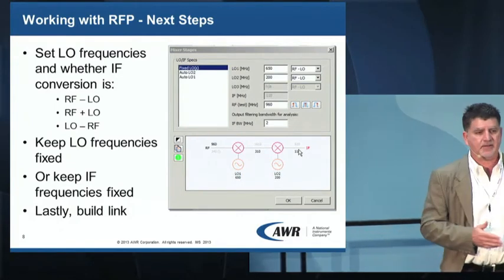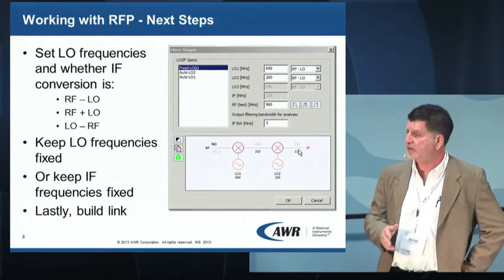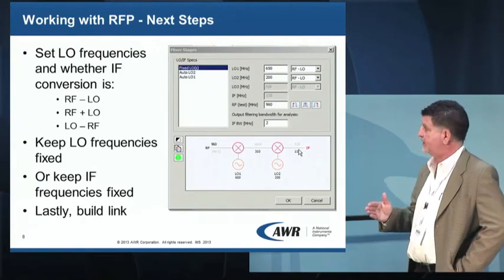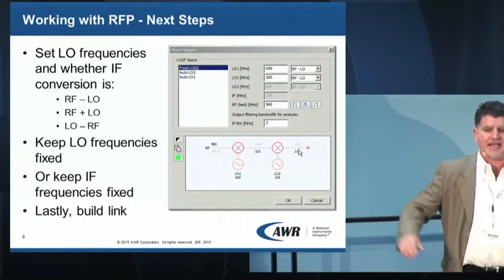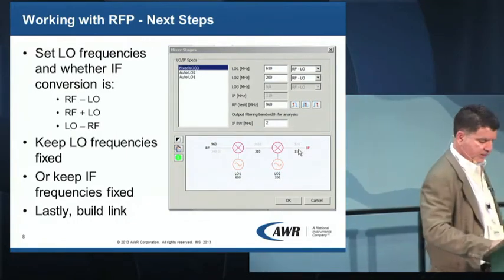And you can keep the LO frequency sweep, you can keep the LO frequency fixed, or you can keep an IF frequency fixed. And ultimately, when you're in this type of environment, you can further analyze that particular mixer model that you're working with. And what does that mean?